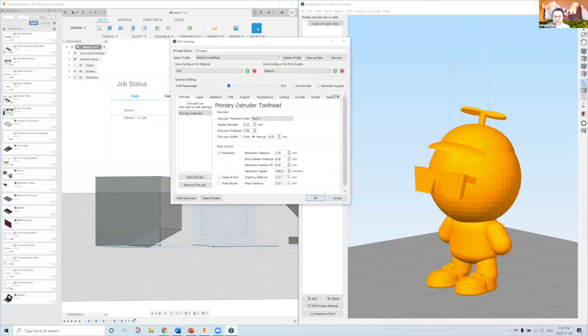And yeah, so here's some of the other things I've been talking about, right? So the nozzle diameter is whatever your hot end is from the manufacturer. So that's set. Extrusion multiplier is what you can tweak to make sure that your printer is extruding sufficient material. So I can change that to 1.2 if I want to make my printer print at 1.2, 120% the material it extrudes originally.